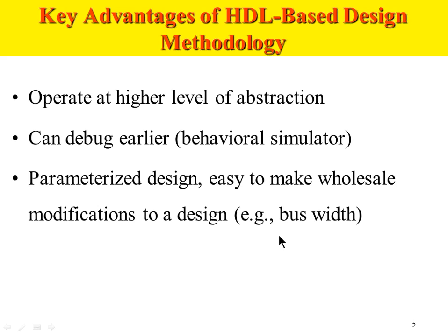In case tomorrow I want to change my design from 8-bit processor to 16-bit processor, all I have to do is change it at one place. So wherever it is declared, the parameter called bit width will change from parameter bit width equal to 8 to parameter bit width equal to 16. Throughout my design, I'll be using the label bit width. So instead of 8 bits, it will be 16 bits. I can make a lot of changes in a single go basically using this concept. This is not possible in schematics. This is possible in a language based methodology like a Verilog based methodology.